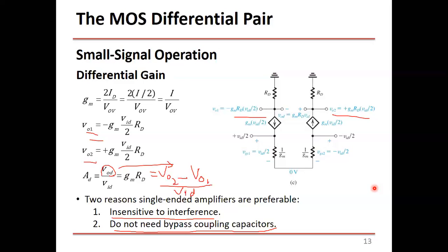Are we still doing this lab then? Yes, we're going to do this lab. I'm going to send you some files to do it in Multisim. It's not going to take much time. You just build the Multisim circuit, take the measurements, and the output will be plotting the characteristic curve, V out versus Vn.